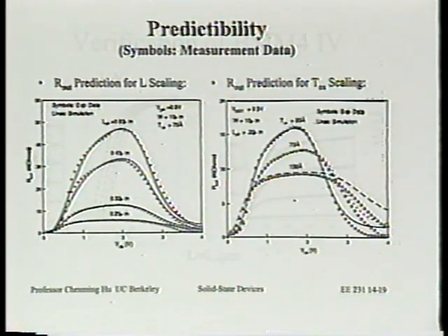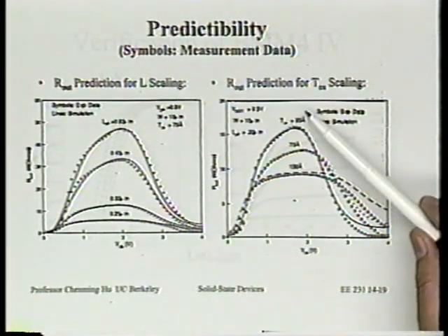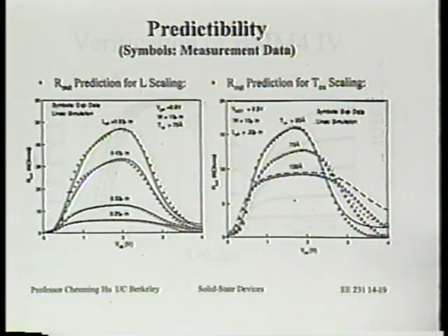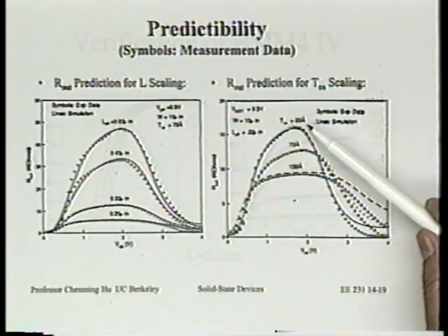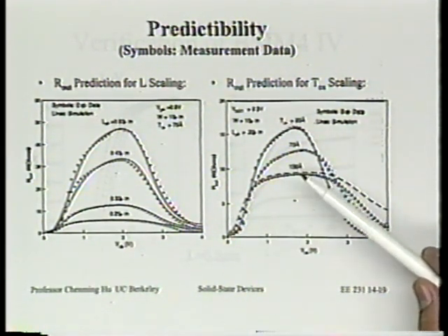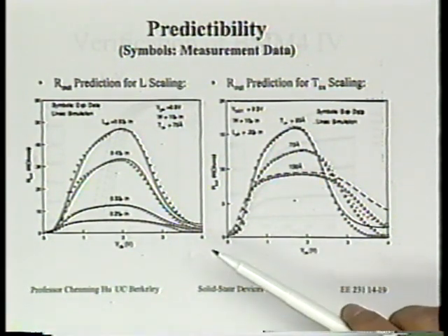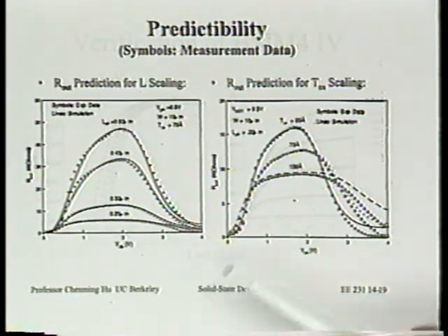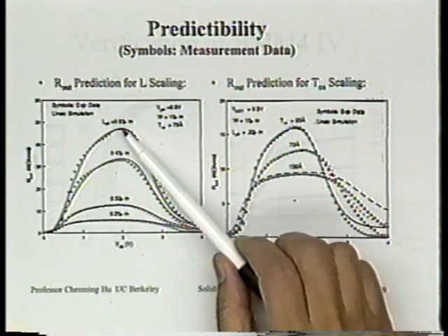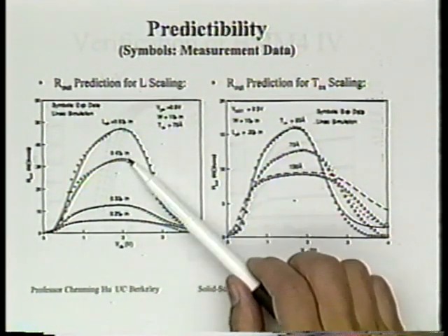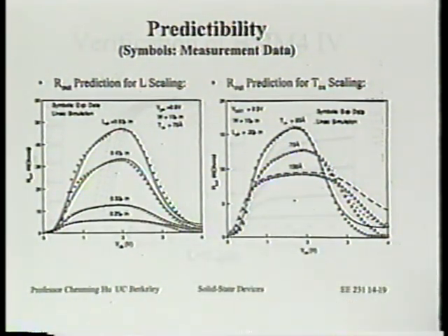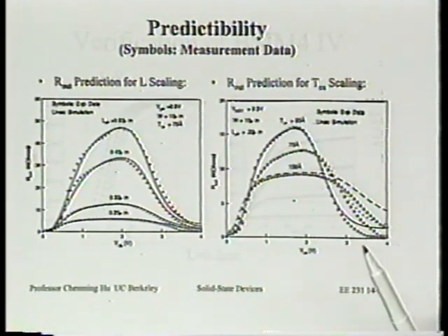What do we mean by data? You take transistors, and first of all, the students actually made these transistors in Cory Hall on the 5th floor in the microlab, right? And he would vary the oxide thickness, and he would vary some doping concentration, and certainly when doing the measurement, there will be different channel lengths to use and different VG. Different channel lengths are available here on the left-hand side, right? And he will vary VD. Of course, he would also vary VG. But in one plot, you cannot show everything. So here we just show you the two things that you usually don't see.